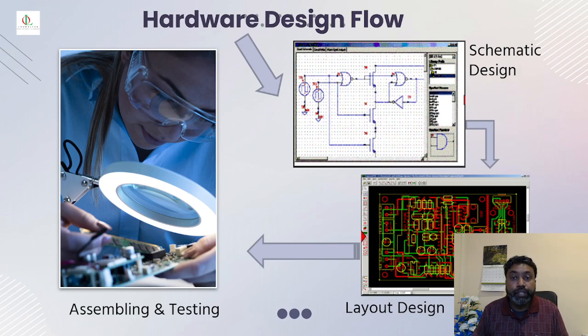First, the flow goes with the schematic design. Whatever you want to see in the PCB design, it's all connected through components with wire connections to complete the schematic. Then you convert the schematic to a layout. Layout is like a pre-PCB where you route it, and the 2 different colors show different layers, like a top layer and a bottom layer, just to give a differentiation for manufacturing and also for your debugging.